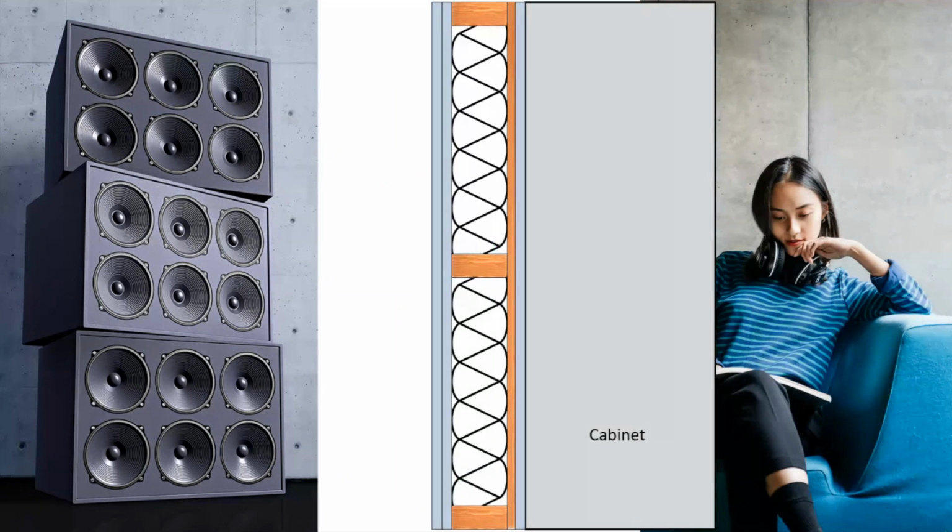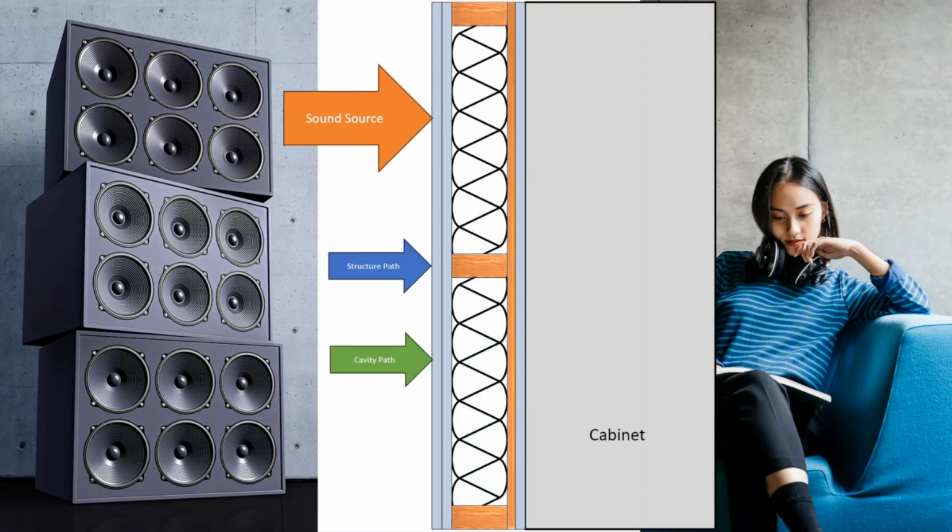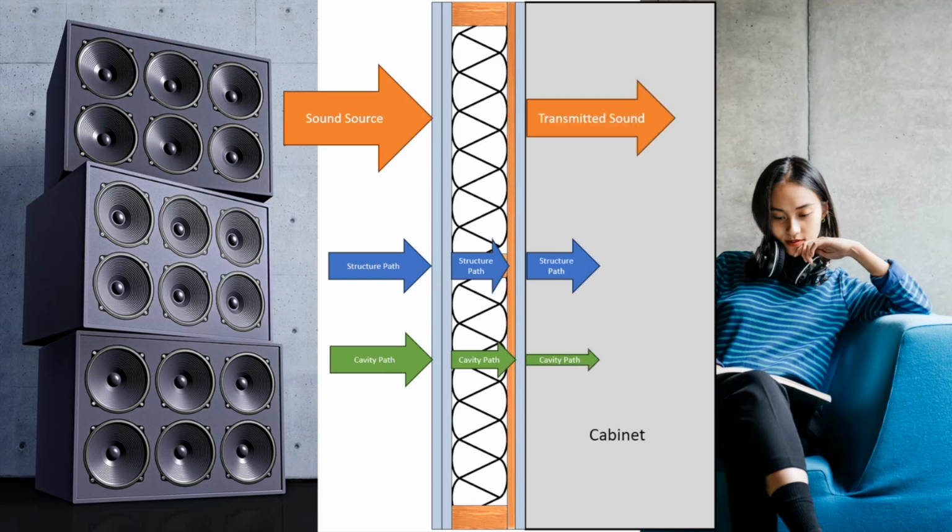An alternative is, say you've got cabinets, and here in the Portland, Oregon area where I worked as a consultant for a long time, we see a lot of apartment walls, 2x4 wood studs, RC. And when they go to mount cabinets, they'll just put in 1/2-inch plywood or OSB, sort of a shim. They'll put it in between the resilient channel or in place of the resilient channel, screw the cabinets through the drywall, through the 1/2-inch plywood and into the studs. So then you create this continuous structural path all the way across that transmits more sound, and you get more sound overall transmitted into the space.